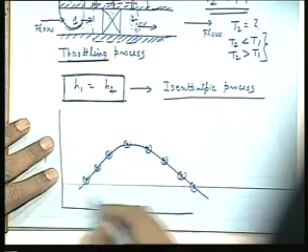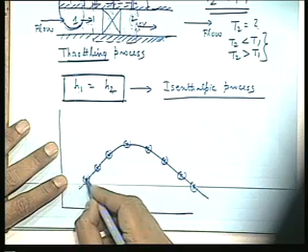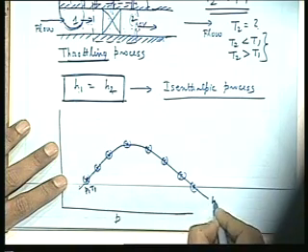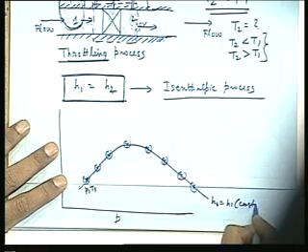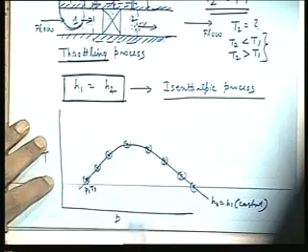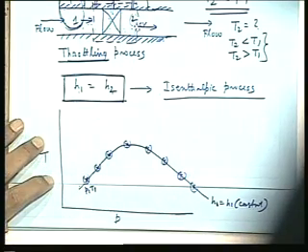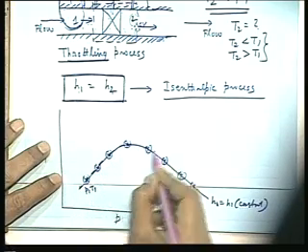The curve will look like that. This is an experimental fact. What is this curve? Let this point be P1, T1, and this is H equal to H1 constant. That means by doing these experiments, I can plot different points on the PT diagram, and this can be joined by a dotted line because this does not show a thermodynamic process.